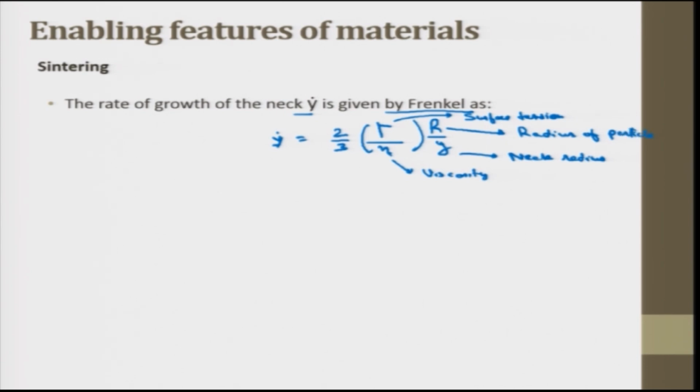So, solid state sintering of metals and ceramics is limited to their pre and post processing, since the times required to accomplish significant densifications are long, and rapid manufacturing of metals using processes involving powder spray, direct SLS provide high energy for melting and flow of liquid metal, rather than solid state sintering that is being described here.